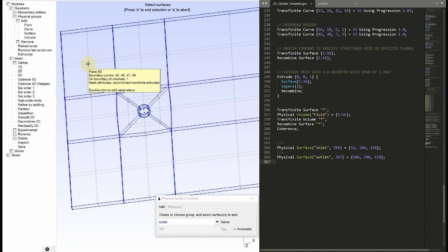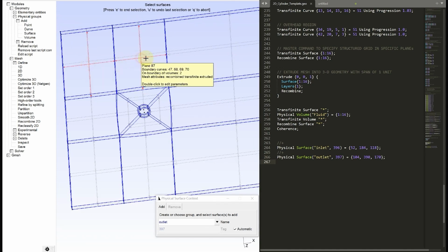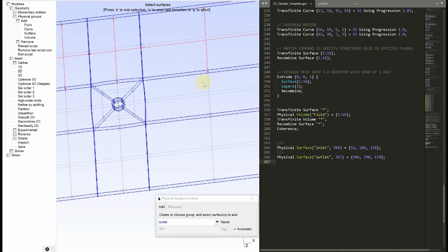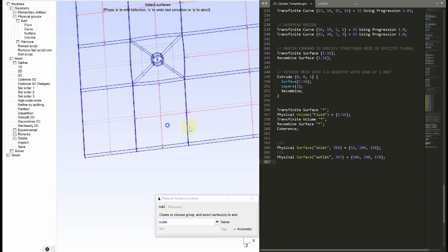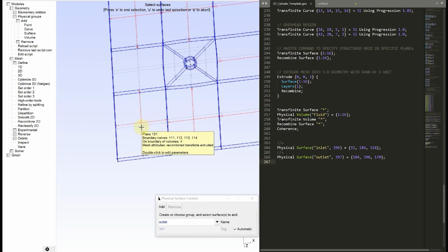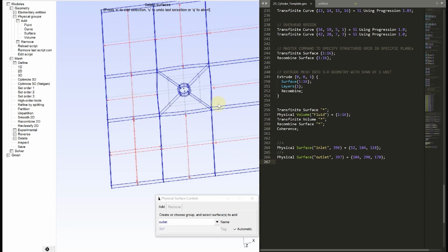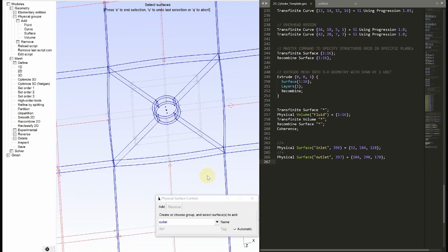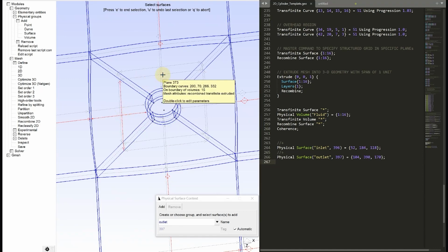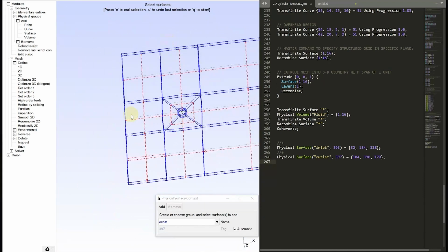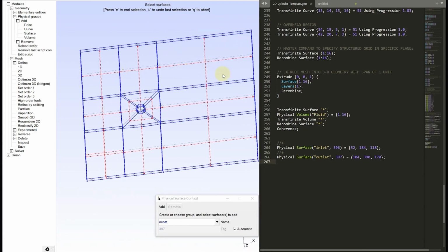So this is going to be a long process. If you are practicing on your own, you can skip this part, but do remember to treat it with care and don't skip any of the surfaces, which will lead to severe errors in your OpenFOAM simulations. Also remember the surface in the square zone as well. Yes, this is the front side.